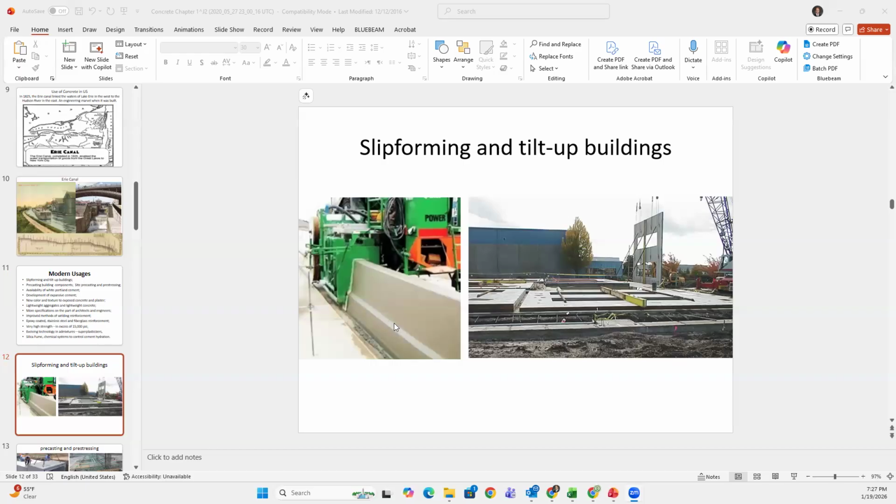Another technology that I refer to as toothpaste is K-rail. There are machines like this that they put concrete mix in, very much like toothpaste. As the machine moves, it produces K-rails for the middle of the freeway. No formwork, nothing. And this machine moves up and down, goes on curves, and these K-rails, the toothpaste, come out shaped, curvy, linear, straight. So these are all very, very sophisticated skills, and only certain contractors do this kind of work.